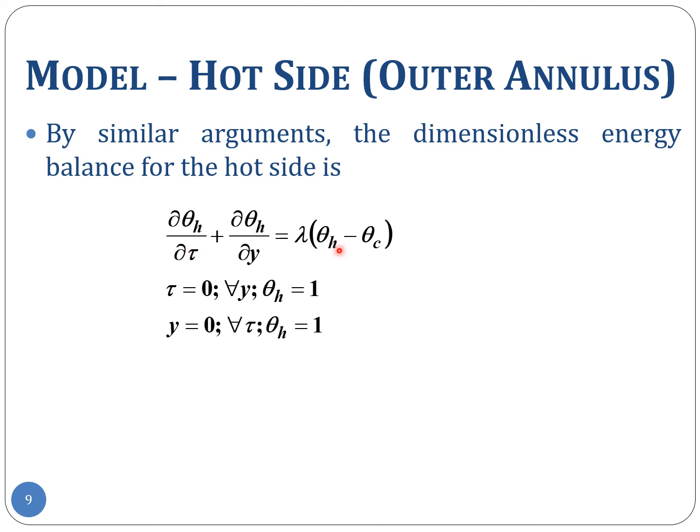Now, on the other hand, if the lambda is very, very small, then this can be fairly small and could be neglected, and then there is not a significant change in the temperature of the hot fluid or cold fluid, either equation, with respect to position or time. So this one parameter can reveal the physics.